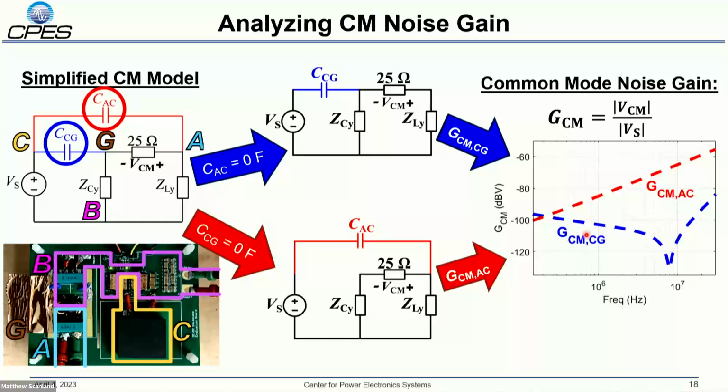Then we'll look at the noise which is generated by the current from area C to area A, and we'll set this other coupling to 0. In this path, the EMI filter actually does not attenuate the common mode noise because once the current flows through this coupling, it faces only a low impedance from your LISN and your Y capacitor branch.